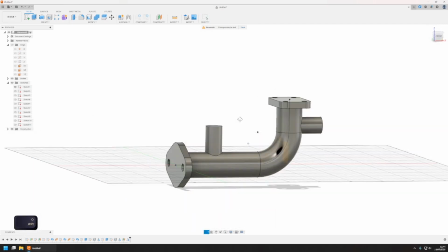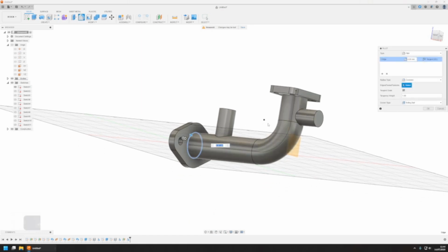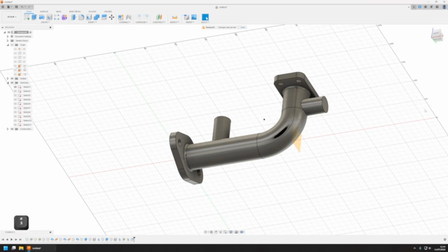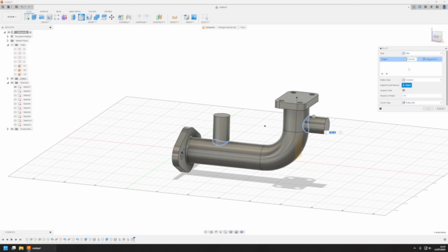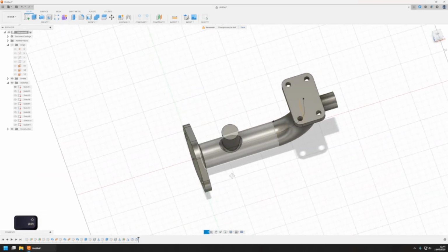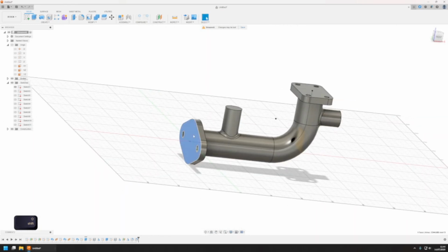Okay, now you can go ahead and add the fillets. You should always try to do this at the end. This looks like, yeah, 3mm should be fine here, and maybe you can add 5mm to this side. But this doesn't really look like a pipe, because a pipe needs to be hollow. And to do that, we just need to create another sweep, or rather 3 sweeps.